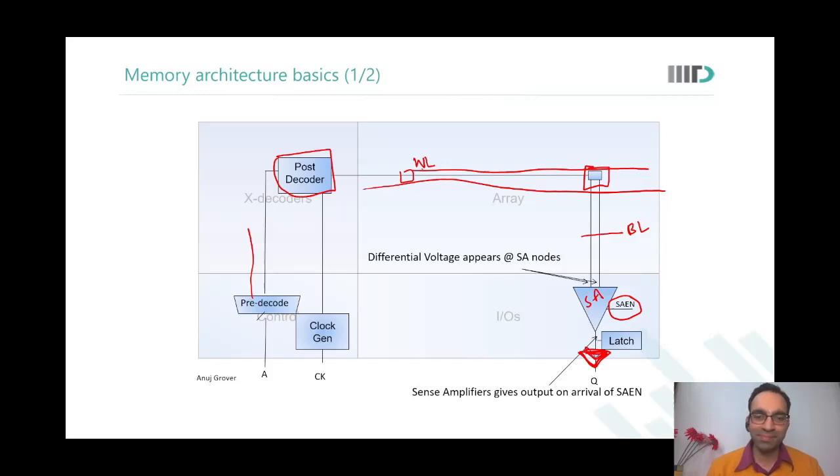Okay, and after the sense amplifier, you have the output buffer. So what exactly is it offering here, the output buffer? A sense amplifier would generate some output, 0 or 1. But the output may actually see a load of 200 picofarads. If you want to drive that big a load, you need some buffer. Buffer is just a buffer.